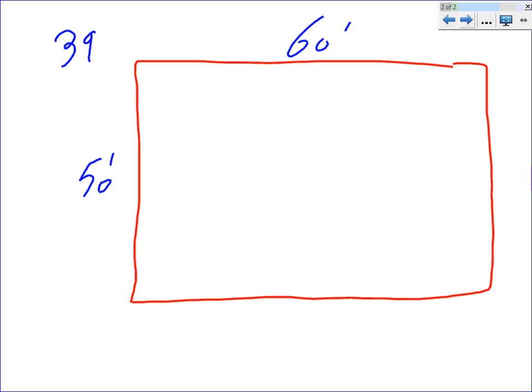So I have 39 fixtures. If this were a square, I would just take the square root of the number, the square root of 39. Obviously, the root of 39 is not a whole number. To find how many rows and how many columns I need, in a case like this, instead of 39 I'm going to add an extra fixture and make it 40, just to place them evenly. That's a decision that you make.